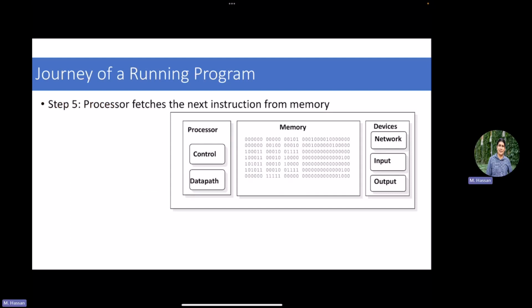Okay. So generally I fetch the next instruction if I'm dealing with branches. Then the simplest format of operation is: fetch an instruction from the memory, decode it to understand it, send the selection lines to the data path. The data path will execute, and then the control will bring the next instruction from the memory and keep doing this all the time. Good. So a third observation: if I'm doing this in that way, which is fetch one instruction, decode it, execute it, and then bring the next one, this is completely inefficient, right? Why is that the case?